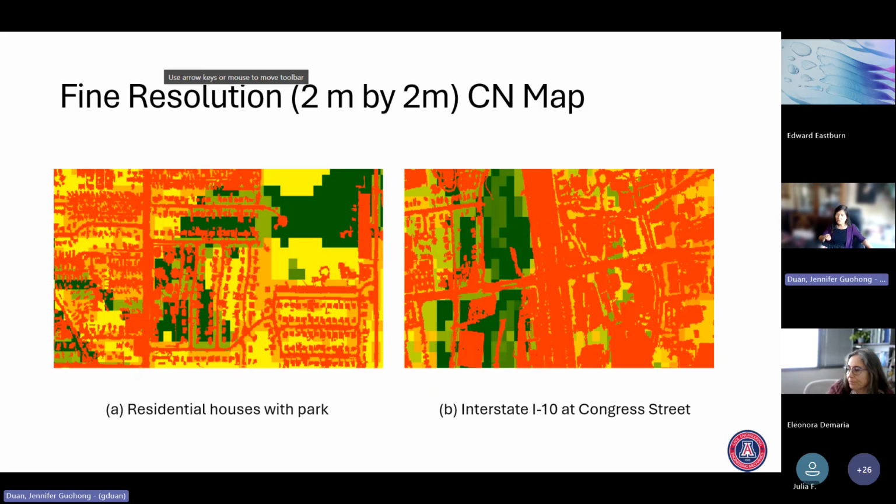They couldn't do this phenomenon: a pond is at low elevation, it fills up, and when the water level is high, it flows down to a lower surface elevation, not a lower land surface, but a lower water surface. So these are two different concepts. If you're using the kinematic wave, you cannot address this fill-and-spill flow condition. You must use the dynamic or diffusion wave. I don't believe they're addressing this either, because it's a slope-dominated phenomenon.